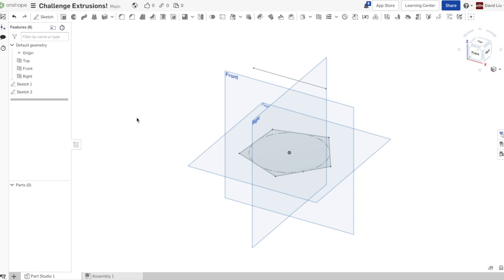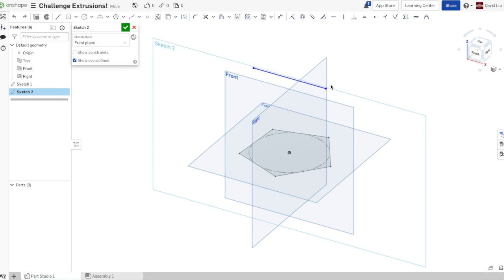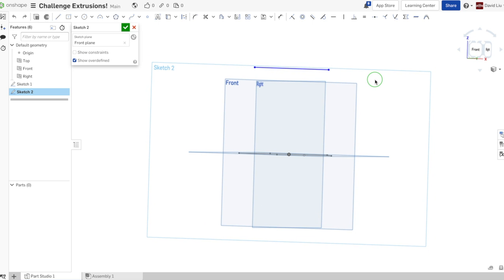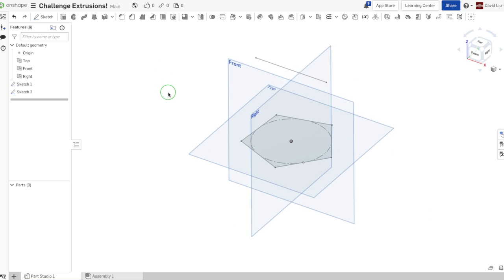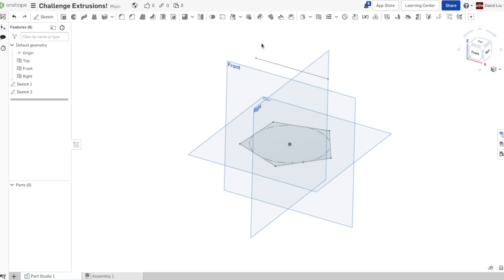Okay guys, so here I simply created a front plane sketch that just consists of a line. Pretty simple stuff, just go into sketch, then go into front plane, and then just do a line. You don't need to dimension it. There's really no point in dimensioning it even if you want to. Make the line pretty far from the midplane. There's really no dimension to do that, just make it pretty far. Okay, now using that line, we're going to create something called a line angled plane.